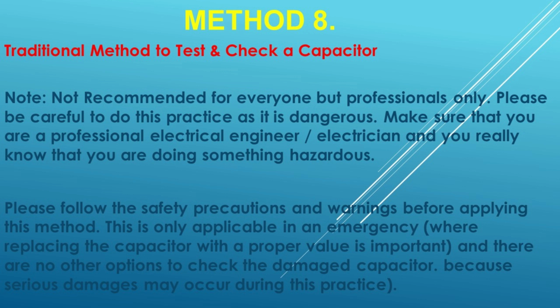For proper safety, use a 12 to 24 V DC source in case of both polar and non-polar capacitors with a 1K ohm to 10K ohm, 5 to 50 W resistor. The resistor should be connected in series with the battery and capacitor positive terminals. This way, it will reduce the excessive current while charging the capacitor.